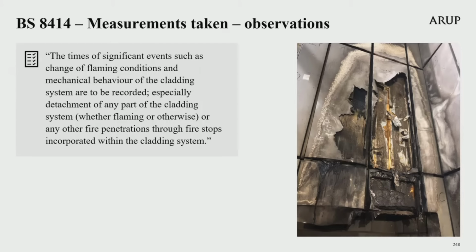Secondly, visual observations of significant events are to be recorded. The standard states, the times of significant events, such as a change of flaming conditions and mechanical behaviour of the cladding systems, are to be recorded, especially detachment of any part of the cladding system, whether flaming or otherwise, or any other fire penetrations through fire stops incorporated within the cladding system.